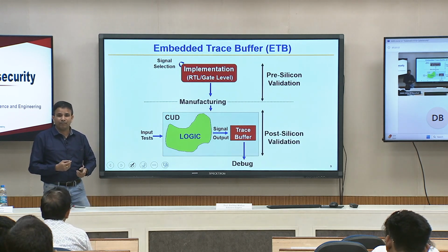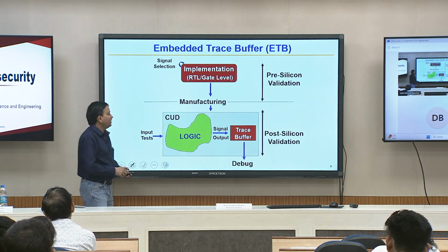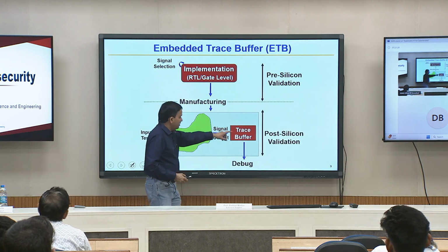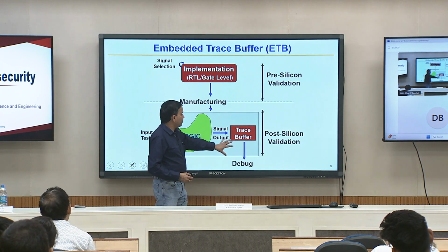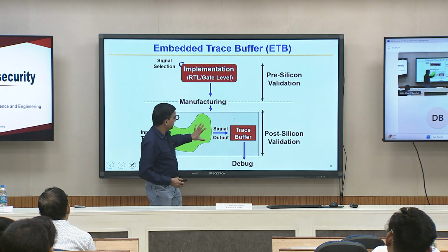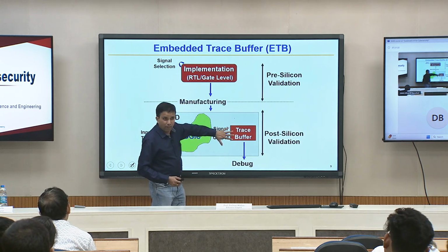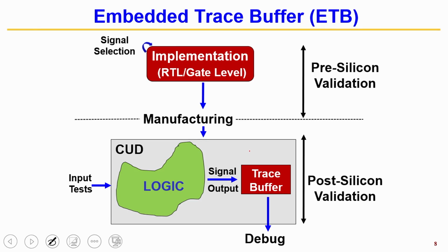So, in general, how do you access the trace buffer? In general the trace buffer is dumped through the debug port. In an ARM processor, for example, it is not like all the signals are hard coded and completely wired, with the only connection being through the debug port. Internally you can choose which variable you want to trace, and internally registers can be read and written through that. So in that kind of software controlled trace buffer you will be able to download those values.